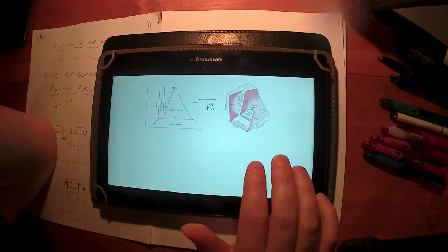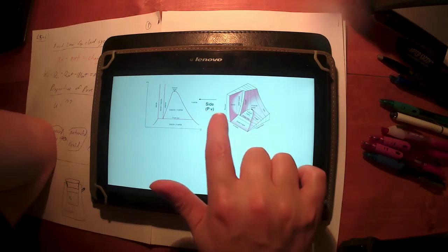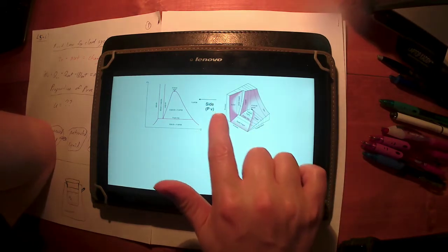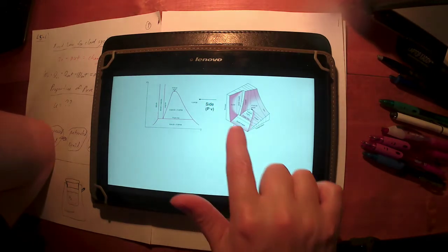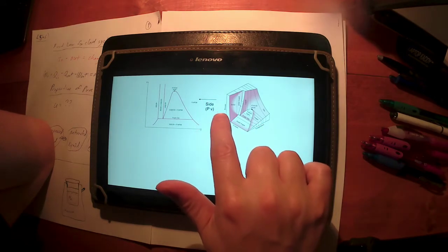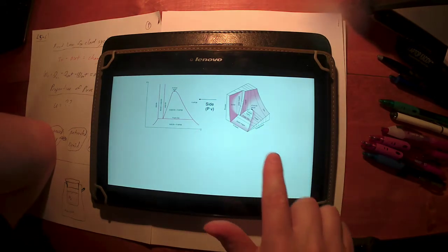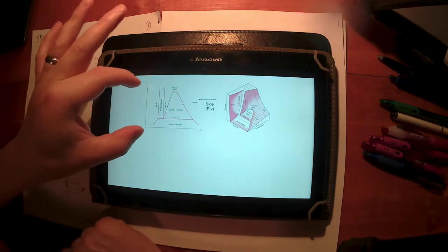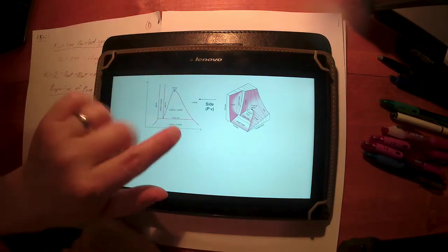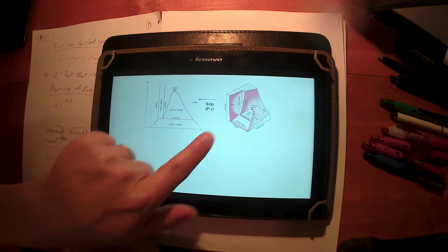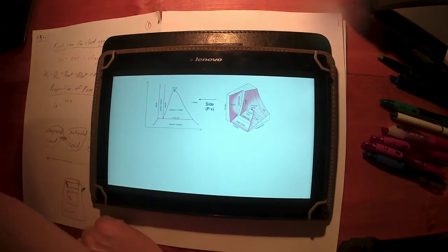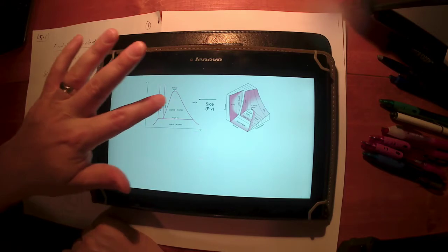So if we do that, if I say, well, this is pressure and this is volume, vertically up and down is pressure, and this kind of down and to the right is increasing volume, so up and to the left is decreasing volume. So this chart right here, this PV diagram, would be what would happen if I looked straight down, if you will, the temperature axis. If I looked right up into the direction of temperature, this would be the projection that I would see.